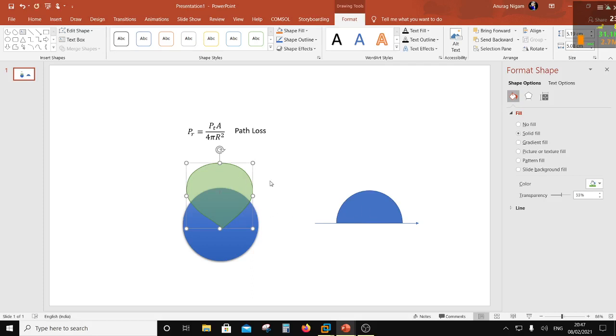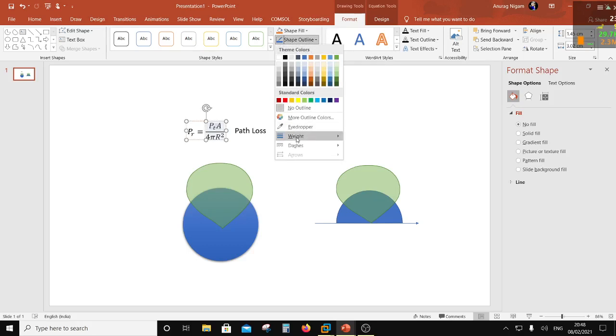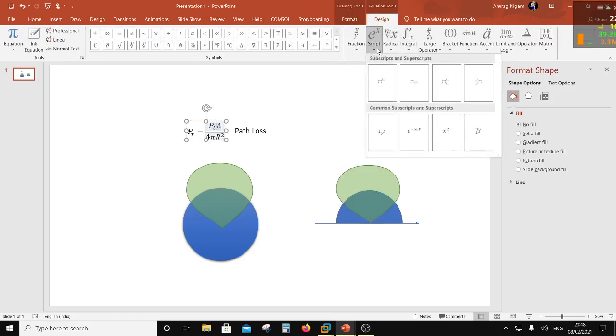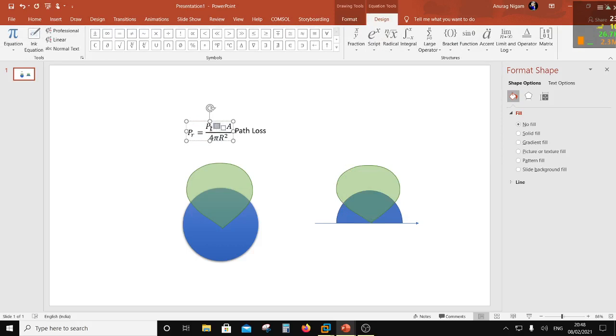Sorry, this one is radiating this way, correct? So now it is the same amount of power, but I'm seeing a certain antenna gain, right? And that antenna gain is AT. So the power which is going to be collected for isotropic will be PT by 4 pi r square, right? But if I give the antenna a certain directional gain, then the power received would be higher than that, multiplied by the transmit antenna gain.